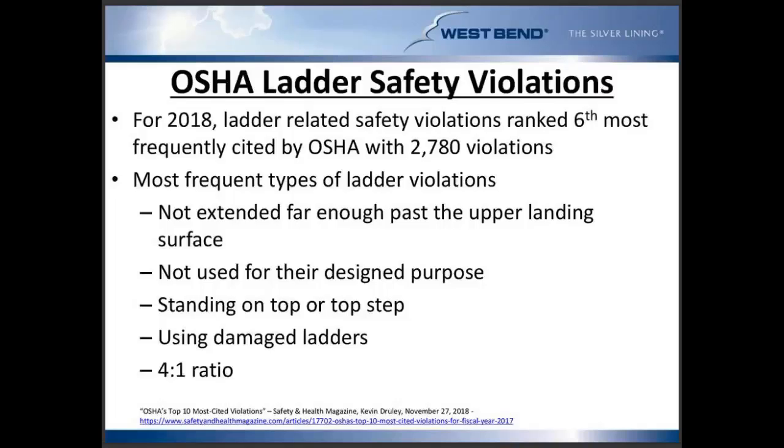I actually, prior to coming into this webinar today, looked, and the 2019 numbers are out, and surprise, surprise, ladder safety violations are number 6th again as far as most frequently cited standards. So this likely isn't going anywhere. OSHA is going to have a very close eye on ladders and again, proper and safe use. And when looking at that, the types of violations that OSHA was seeing was not extending far enough past that upper landing surface. And we'll get into that in a little bit more detail, how far or how long that ladder needs to be extended to in order to safely step onto an upper landing surface.